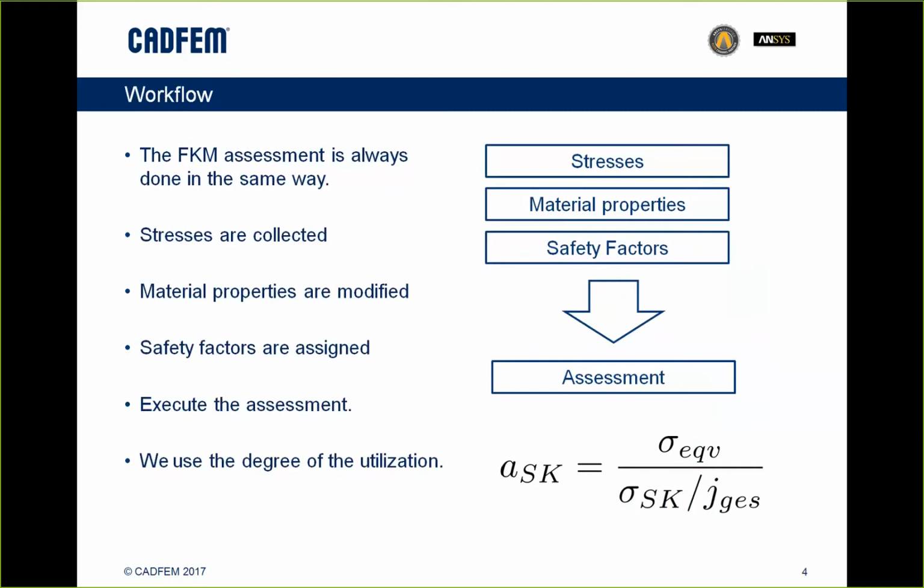If I had a 1 meter part, so 1 meter in diameter, and I would heat that up so it will really be glowing, and I tried to cool it down, I will see that I no longer have the temperature control because this big chunk of metal won't cool down easily.